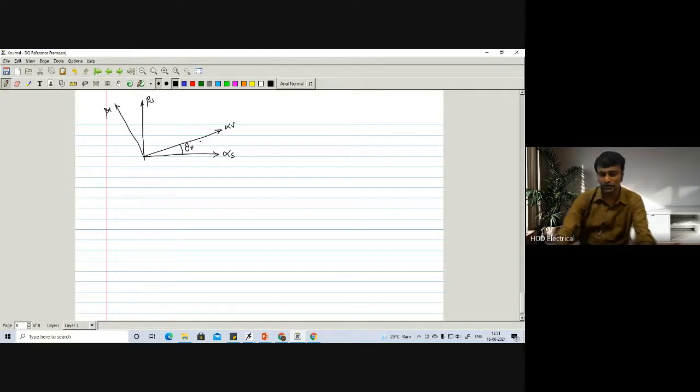This is how we have taken the 3-phase to 2-phase system into account, with a separate winding here, one winding here, in this place and this place. So this is V alpha S, V alpha R, V beta S, V beta R, and the total angle is theta. Now, from this, we have to write the speed EMF term G alpha beta naught.